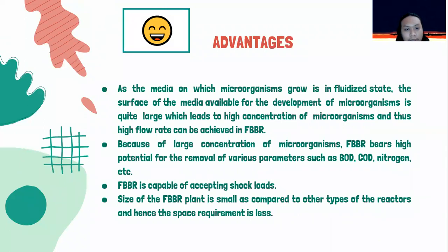First, the advantages. As the media on which microorganisms grow is in a fluidized state, the surface of the media available for the development of microorganisms is quite large, which leads to a high concentration of microorganisms, and thus a high flow rate can be achieved in FBBR. As I explained before, because of the large concentration of microorganisms, FBBR bears high potential for the removal of various parameters such as BOD, COD, nitrogen, etc.